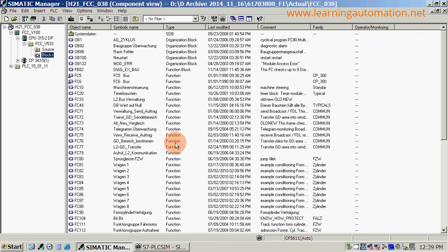Now for the 2 or 3 memory bits that we're likely to use, we'd like to keep memory bits together. For example, we'd want to use, say, memory bit 20.1, memory bit 20.2 and memory bit 20.3. There's no point using memory bit 1.5 and memory bit 100.7 and memory bit 2.6. They're spread about and it's going to get messy.